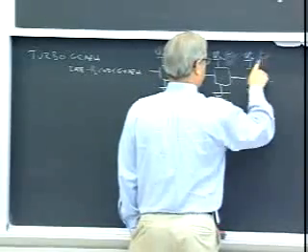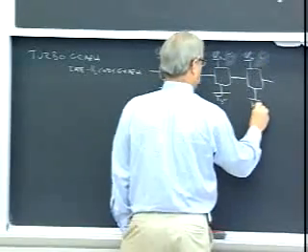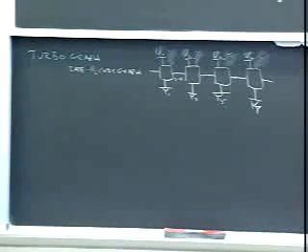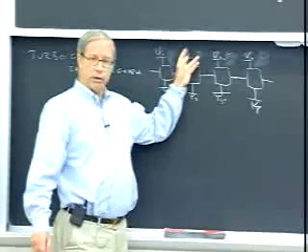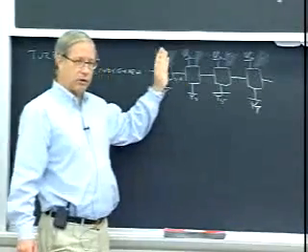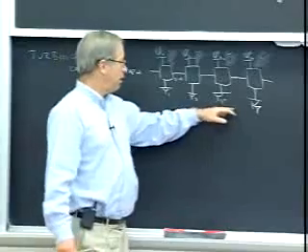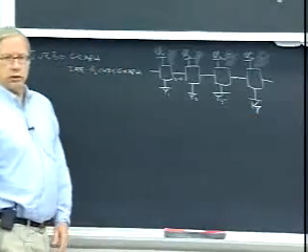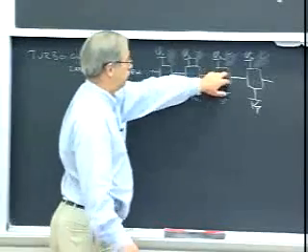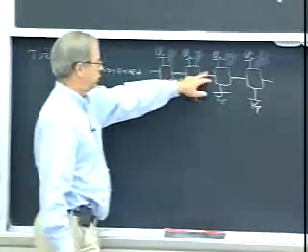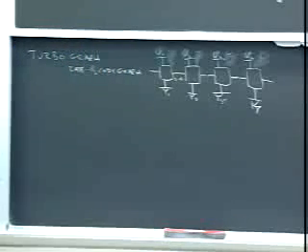But it's all the same thing, right? It's what you've already seen. So I just want you to get used to this way of writing the trellis, the graph of a trellis of a rate 1/2 systematic convolutional code. Here are these systematic bits, which are both inputs and ultimately outputs onto the channel. These are the parity bits, which are only output onto the channel. And these are the branch constraints for each time. And these are the state spaces for each time. So that I can always draw that way.